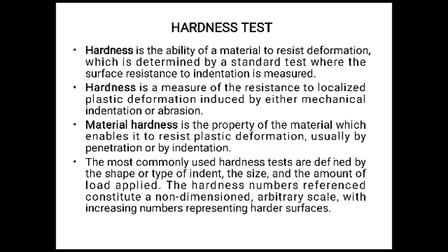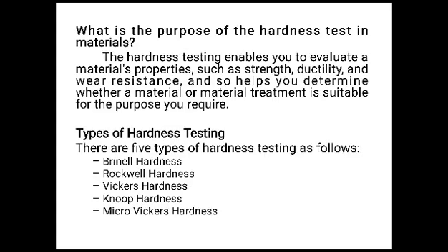In this lecture, we are going to elaborate the various hardness tests. Hardness is the ability of the material to resist deformation, which is determined by a standard test where the surface resistance to indentation is measured. The purpose of the hardness test is to enable us to evaluate material properties such as strength, ductility, and wear resistance, and it also helps to determine whether the material or material treatment is suitable for the purpose you require.